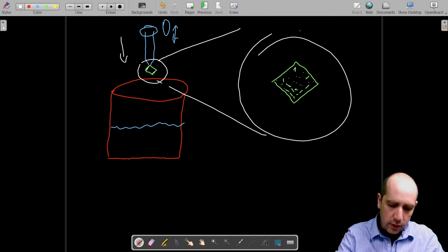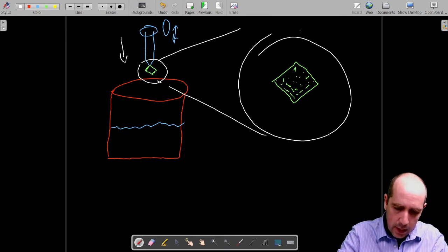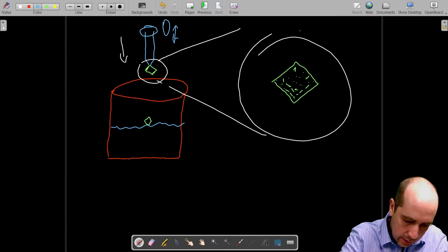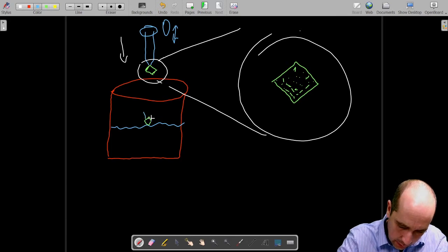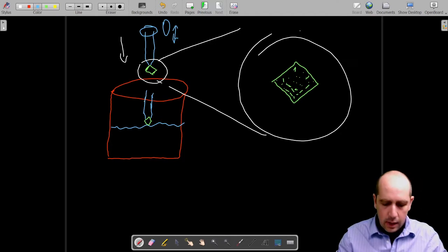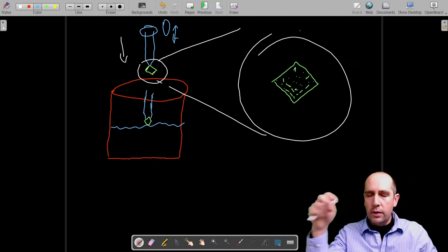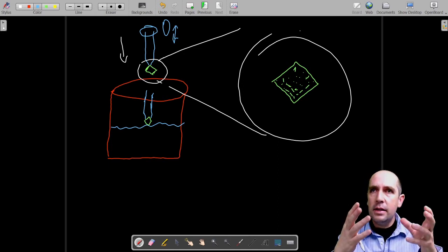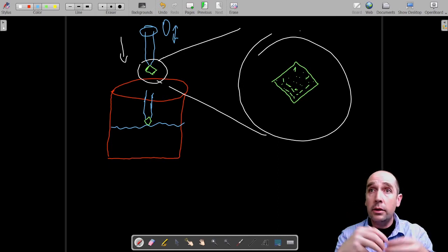And the next step is we bring this seed down to the surface of the melt. The rod goes all the way down to here. We put it in contact with the surface of this liquid silicon, and what happens is the seed is at lower temperature, and the metallic rod essentially can conduct heat.